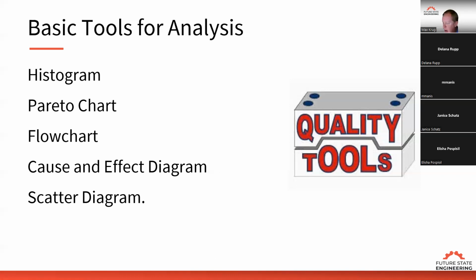I said, okay, let's take data and look at it, right? Do we know what the U value was before we cleaned it? They're like, yep, we know that. Do we know what day we cleaned it? Yep, we know that. Do we know what the U value was after we cleaned it? Yep, we know that. And do we know when the next cleaning happened? Yep, we know that. So we took the data and we took 2 variables. The starting U value, so after they cleaned it, what was the U value? And then how many days it went till it had to be cleaned again, when the U value got down below the acceptable limit.